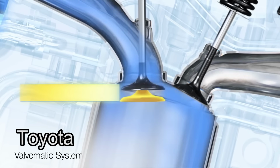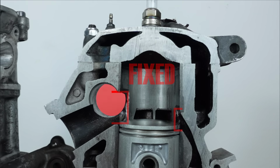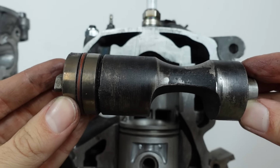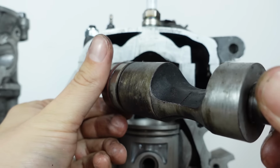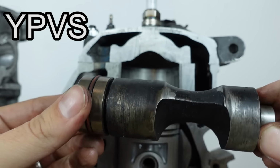In contrast to this, the two-stroke cannot change the position of its ports. They are a fixed part of the engine's construction. But what a two-stroke can do is change the size of the exhaust port. And this finally brings us to the big round hole in the exhaust port. It's meant to house this. And this is a part of a system called YPVS, which stands for Yamaha Power Valve System.